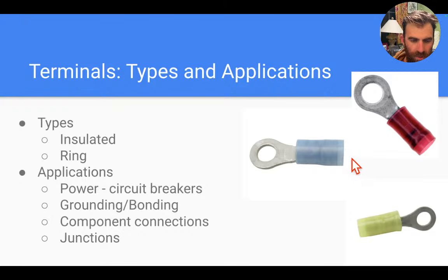But yeah, if you've ever worked on a car or something, it looks like a ring terminal that would go on a car battery. You'd strip the wire back and insert it into the barrel here, and then use a tool to crimp it down, and then a portion of the wiring gets crimped around the metal part of the terminal, and then another portion is just floating into the insulation of the ring terminal here.